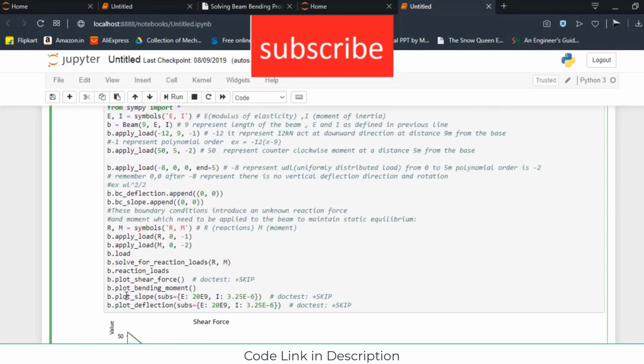In the end what you need to do is B dot plot shear force, so it will plot the shear force diagram. B dot plot bending moment will plot a bending moment diagram. B dot plot slope, so here you need to give the value of E. Here I give the value of 20 times 10 to the power 9, and I is the moment of inertia. I give the values. Remember, all our units are in kilonewton and meter.